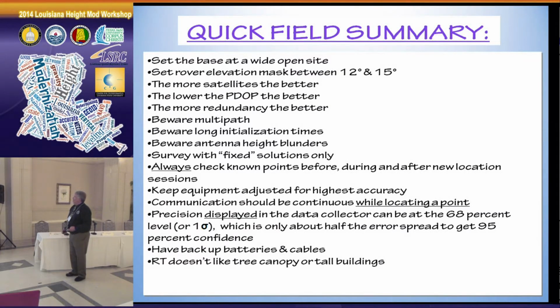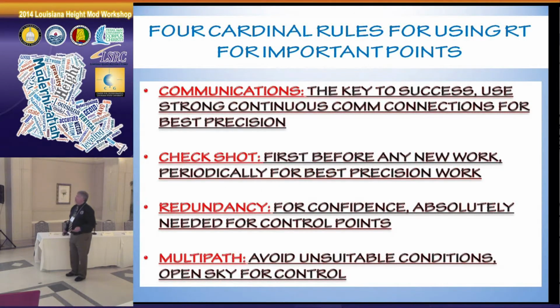There's a summary. I think we talked about most of that. You guys are pretty familiar with most of this stuff. And here are the 4 cardinal rules. Communication strong and continuous for important points. Always get a check shot before you begin work. Always get redundancy for important points, always. And be aware of multipath. Those are the 4 things to do to make sure you have confidence with your real-time work.